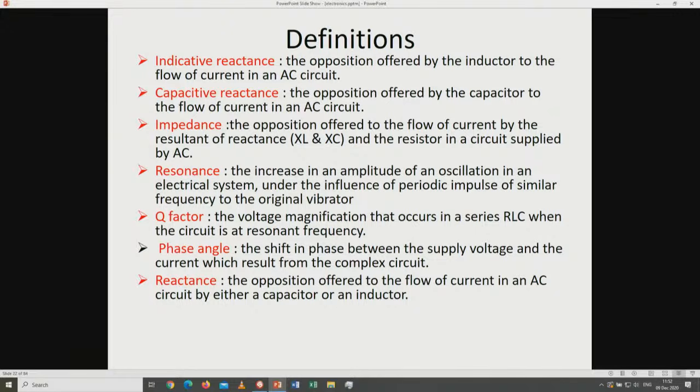And under parallel resonance, we normally say IL is equal to IC. And remember here, our power factor will be 1. Because of the formula of power factor, we normally say it's R over Z. So since R is equal to impedance, our power factor will be equal to 1. And our phasor angle here will be 0.